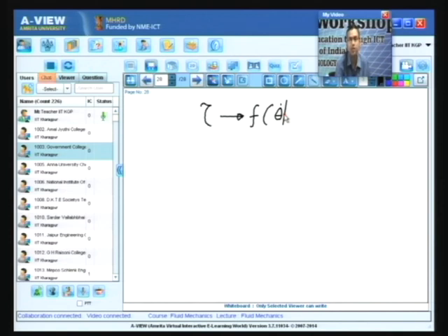For a fluid, force is related to the rate of deformation. The reason is that for a fluid, if you allow more and more time, more and more deformation will take place, because fluid is continuously deforming. So for fluid, rate of deformation is what is important. So tau is related to the rate of deformation, which is given by theta dot.